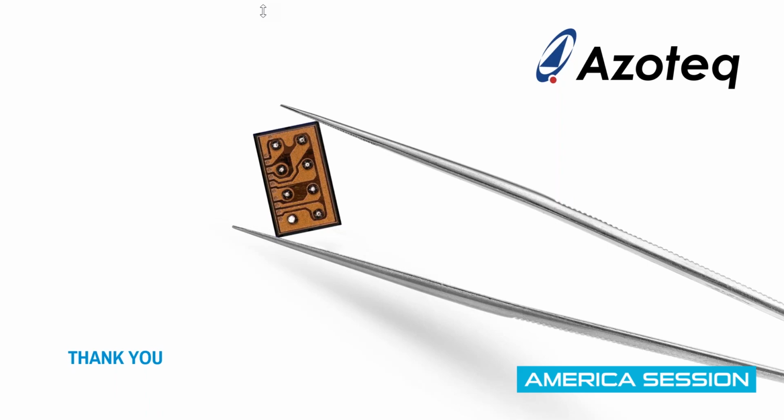If you need more than just the single bit indicating that the threshold was exceeded, you can get access to the raw data over the I2C interface. Otherwise, you are able to adjust certain parameters on the fly. Let's say you want to adjust a threshold or sampling frequency or something like that. You have the ability over the I2C interface.